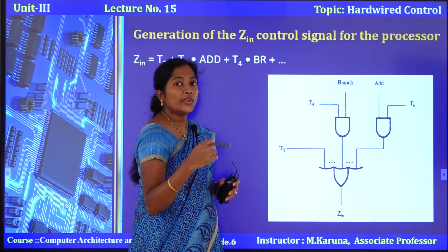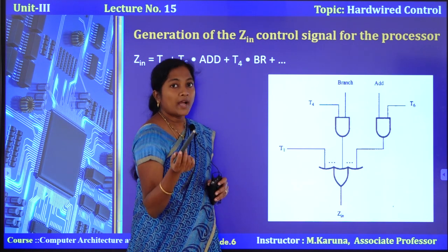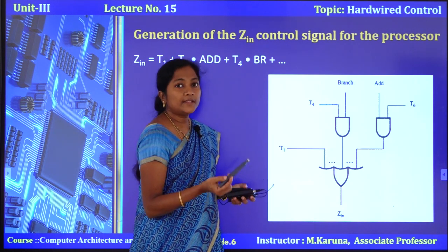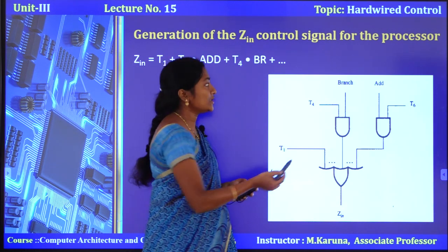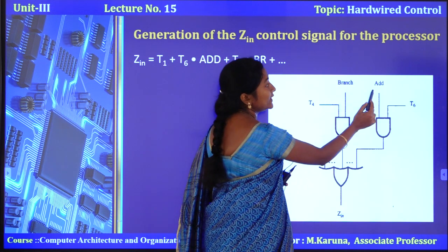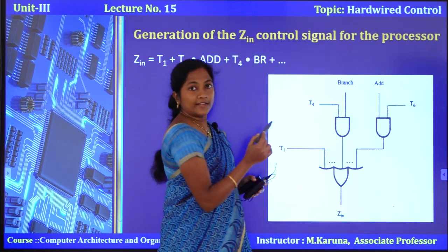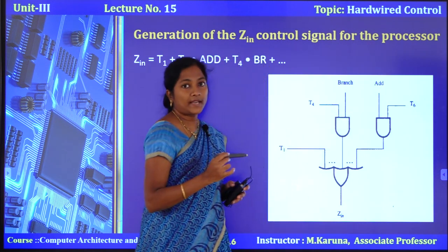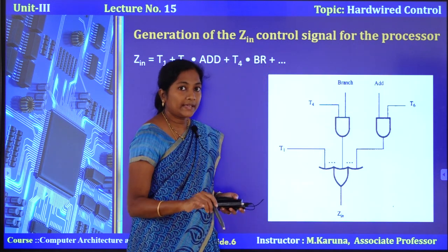Before jumping to the specified address, the PC content will be loaded with the target address. So we need to add the PC content with the offset address to get the target address.